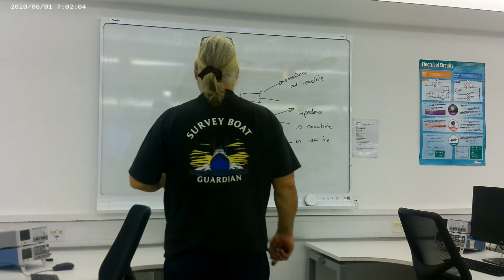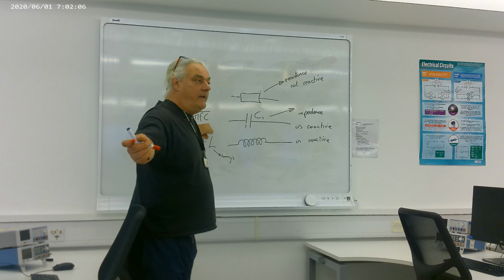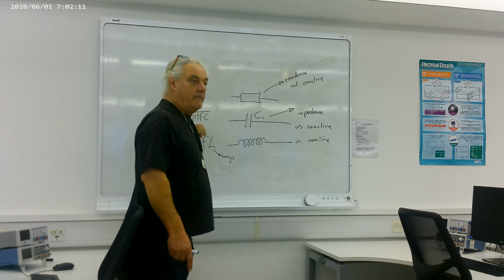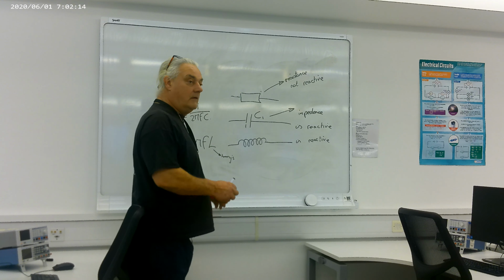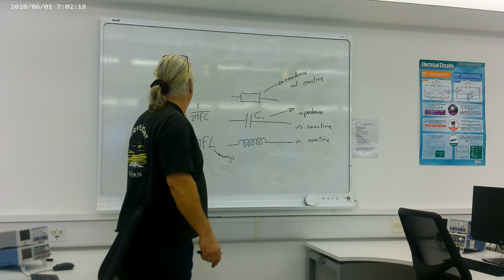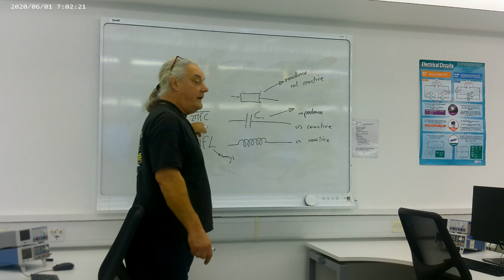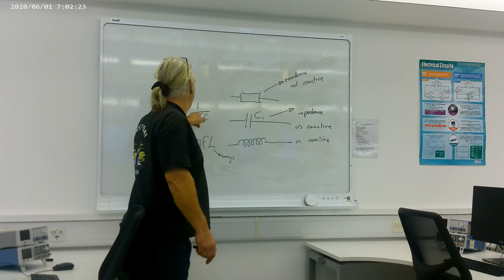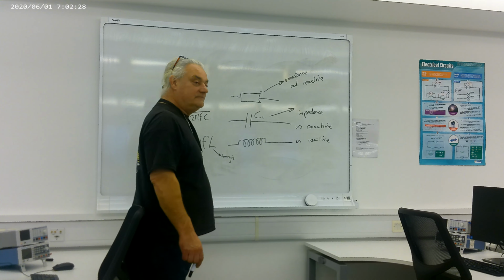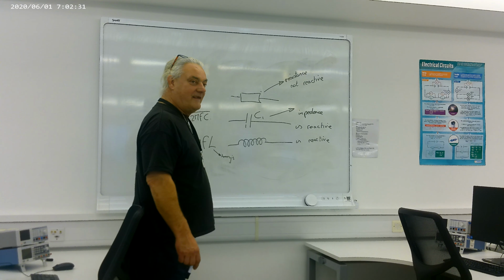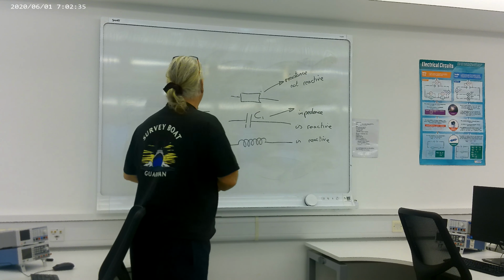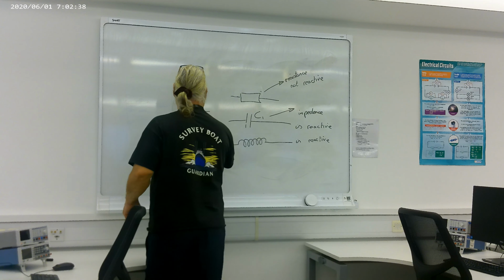So forget capacitance, it's fixed, right? What happens if I increase frequency? It's inversely proportional. If I have high frequency, I have low impedance. If I have low frequency, I have high impedance. Excellent. So in the top one here, if I increase frequency, it means a bigger number divides it. Well, that's what I'm saying. So F gets big.